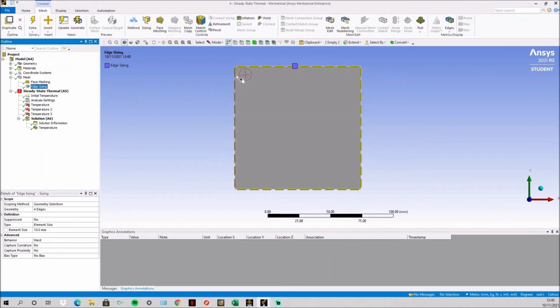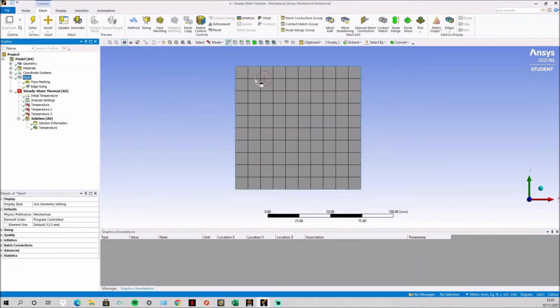So there'll be 10 elements down, 10 elements along, so 100. So the same as the Excel. And this is an FEA analysis, so it's finite element analysis, and it's called finite because you can't do an infinite number of elements, so you have to mesh and get a certain number of elements. And this is discretizing, so we're discretizing this block surface to 100, and then it interpolates the values between here. It calculates them where they cross and then interpolates them so you can cover the whole thing, even though you're only calculating 100 different points.